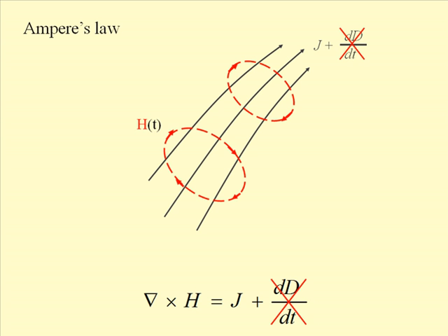So that's Ohm's law. Another important law to understand in electromagnetics is Ampere's law. And Ampere's law tells you that if you have some current density J, denoted by these three black lines flowing from the bottom left to the top right, then circulating around that current density J will be a magnetic field, a circular magnetic field H, as denoted by these dashed red lines. The mathematical form of Ampere's law, written with vector calculus, is down the bottom here for those that are interested in the calculus.